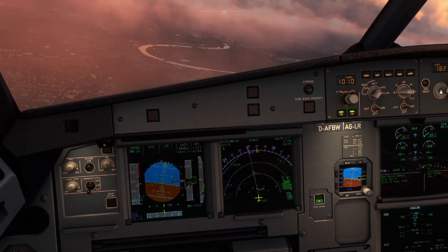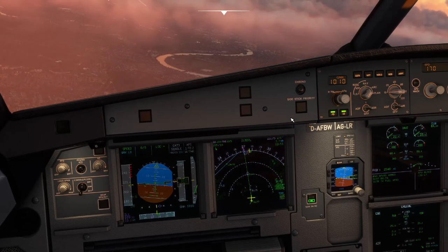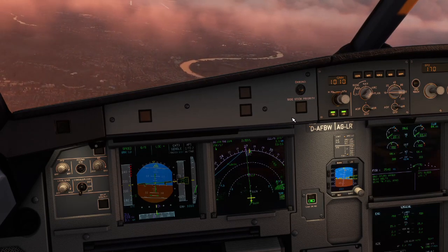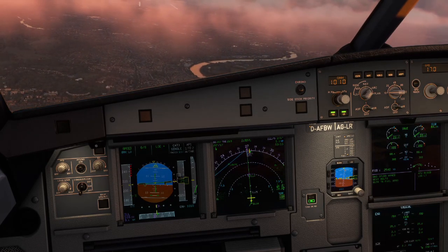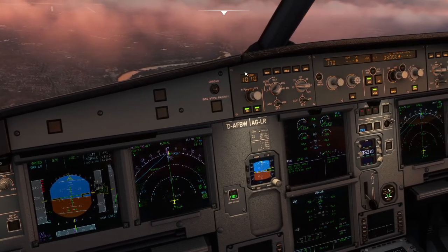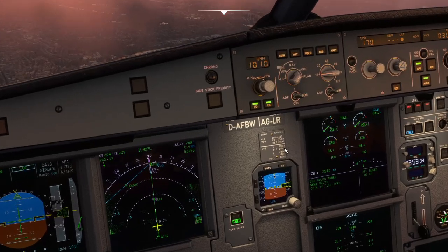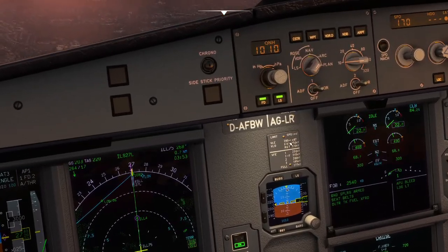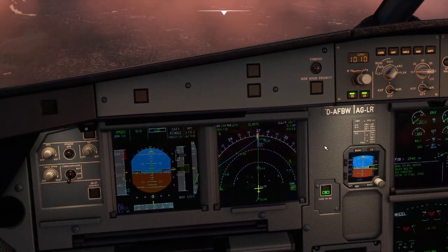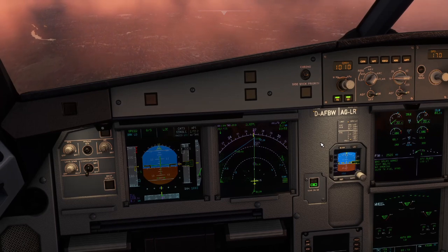Let's start bringing the speed all the way back. She's not going to want to slow down like this, so we've come off that in not a great position, but you know what fixes profile? Correct. Gear. So max gear extension 280, we're below that, and since that profile was not the best ever, that is what we're doing to fix it. The flap limit speeds weren't going to help us out there.